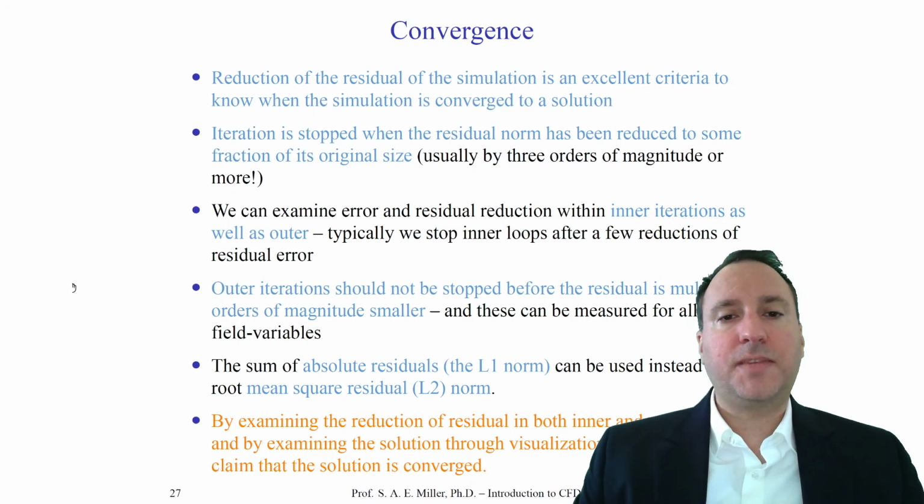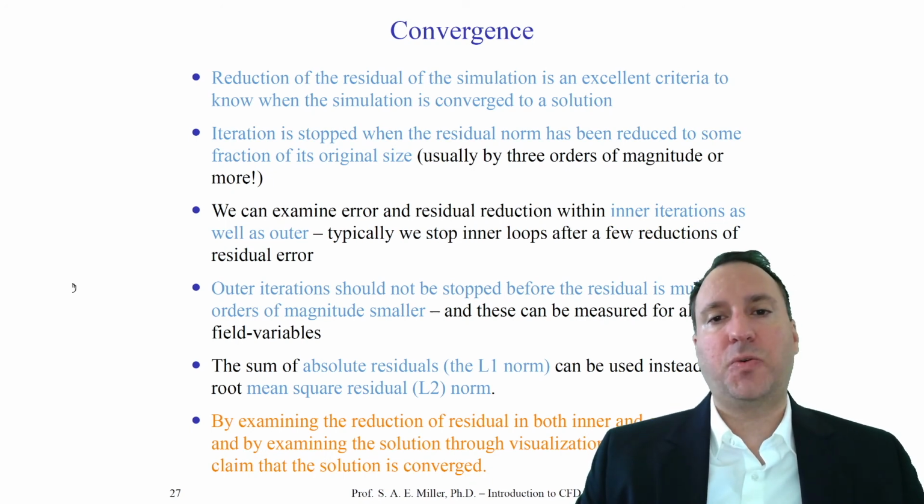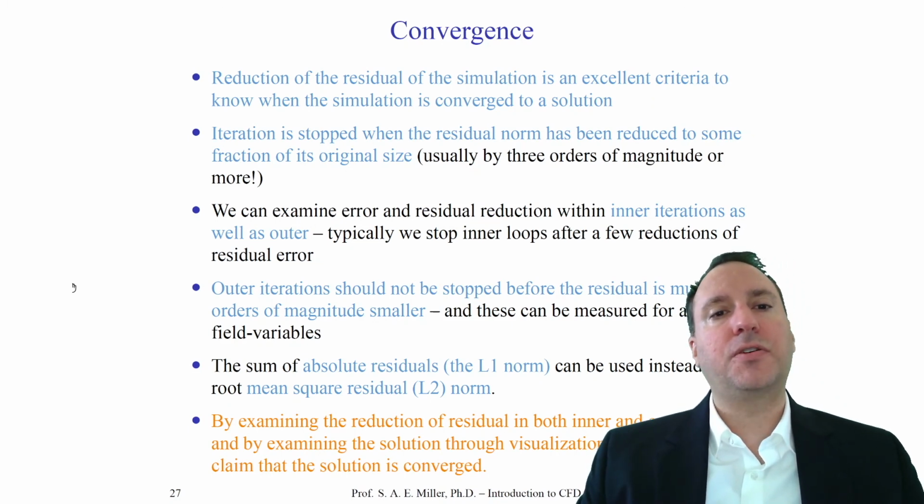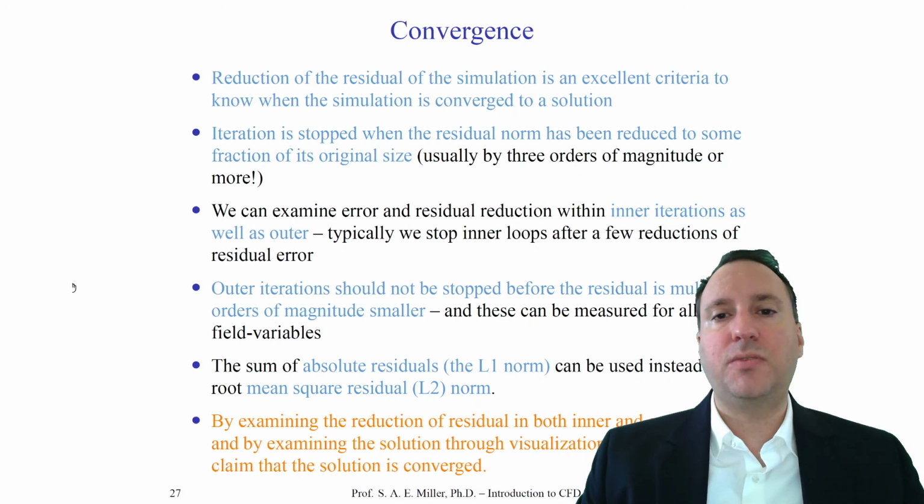So some cases will not have multiple orders of magnitude reduction. Those should be a little bit suspect and treated suspiciously. It could be the case where your residual increases, especially when you have an ill-posed initial condition. This is more the user's fault for not specifying an appropriate initial condition for the equations of motion.